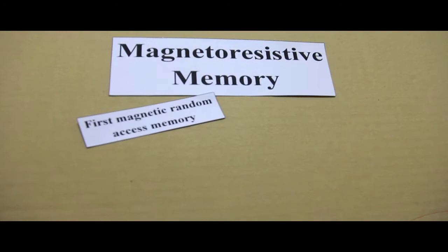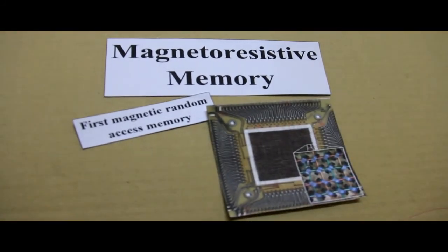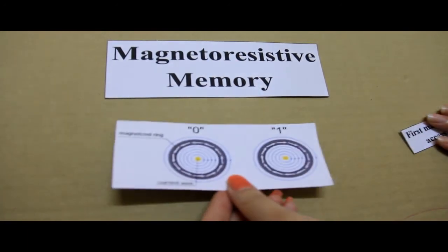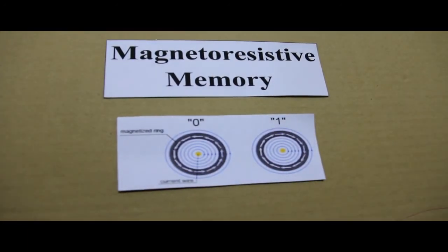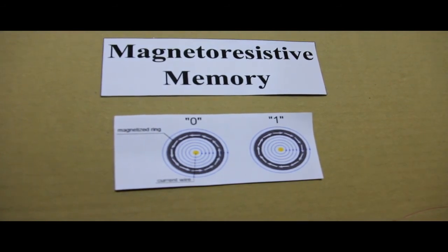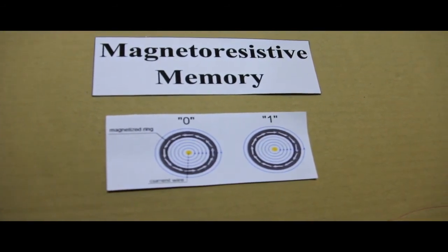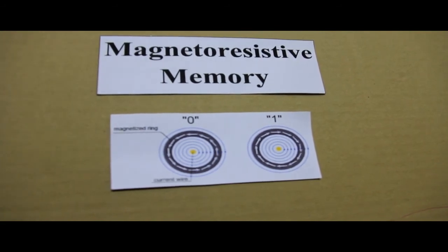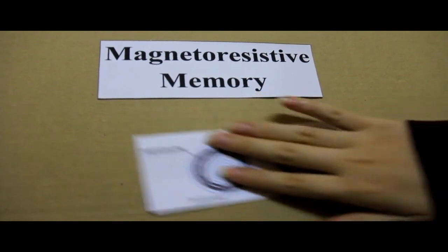The first magnetic random access memories used ferrite rings to store bits of data. To write a bit, the magnetization of the cores was switched by a combined action of currents flowing in wires woven through the toroids. The readout was performed by registering the voltage induced in a wire by the application of a definite impulse in writing wires.